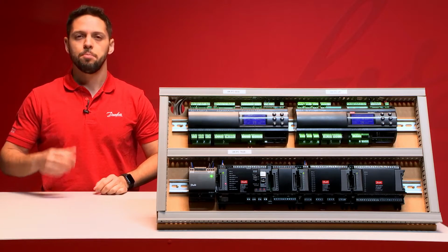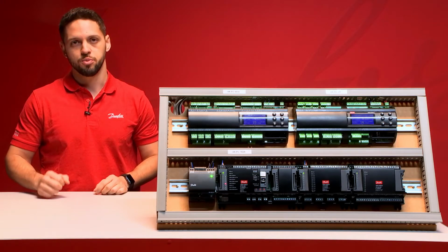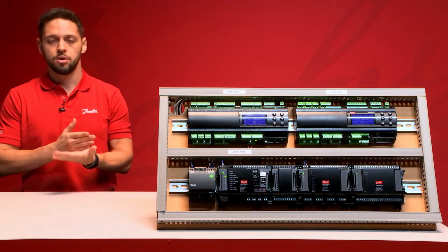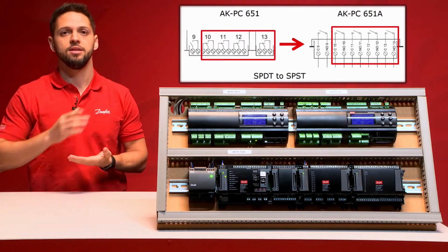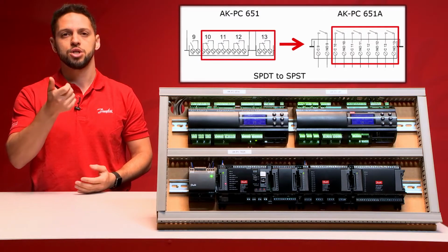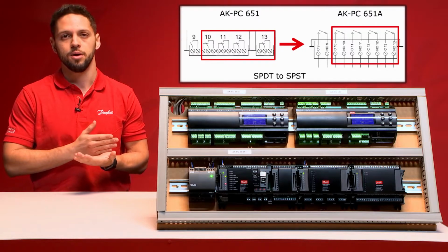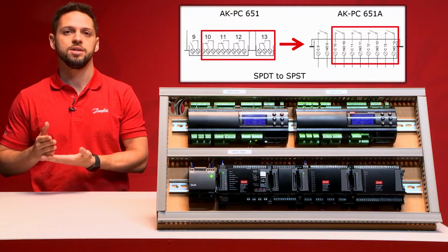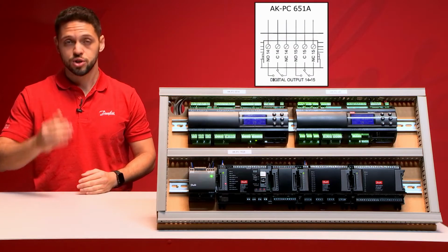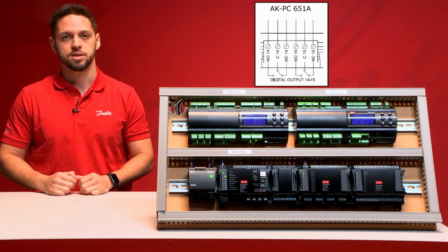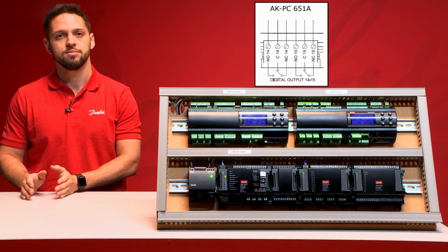So let's point out these small hardware changes. Let's talk about the digital outputs first. From the digital outputs number 10 to number 13, as you can see in this image over here, we have internally changed the model of the relays. So they are not SPDT anymore, they are SPST. It means that now we don't have the normally closed contact anymore. However, if you still need to use the normally closed contact, you can use the digital outputs DO14 and DO15.